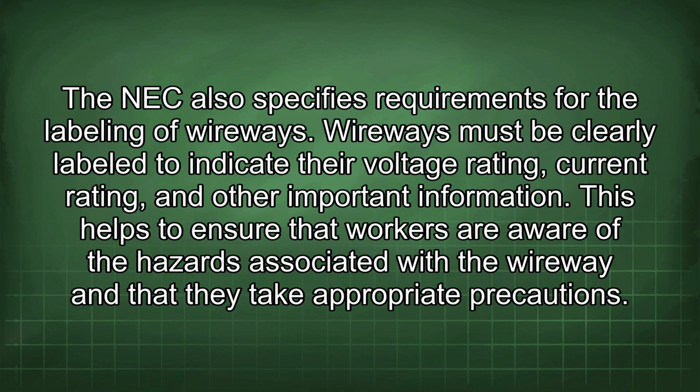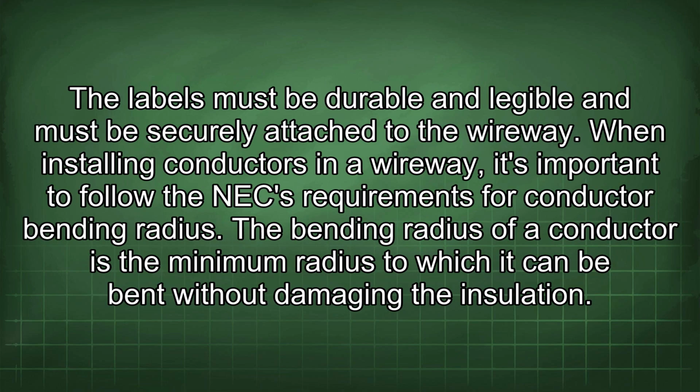The NEC also specifies requirements for the labeling of wireways. Wireways must be clearly labeled to indicate their voltage rating, current rating, and other important information. This helps to ensure that workers are aware of the hazards associated with the wireway and that they take appropriate precautions. The labels must be durable and legible and must be securely attached to the wireway.